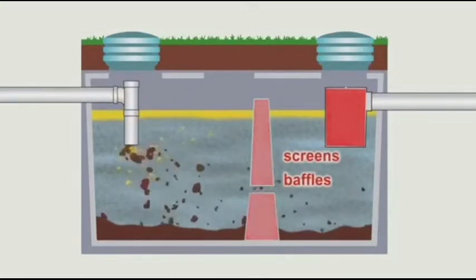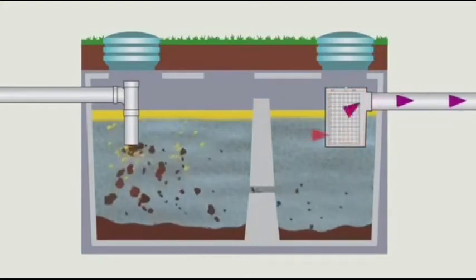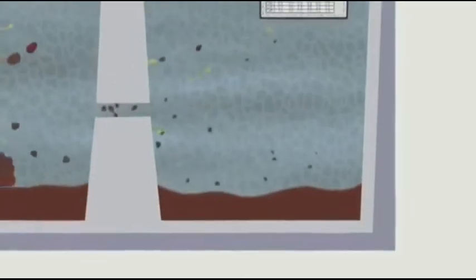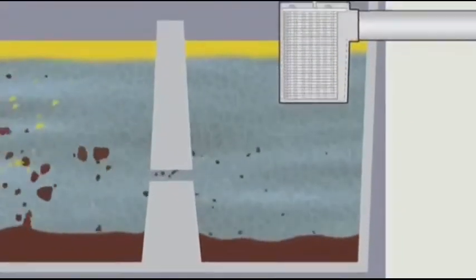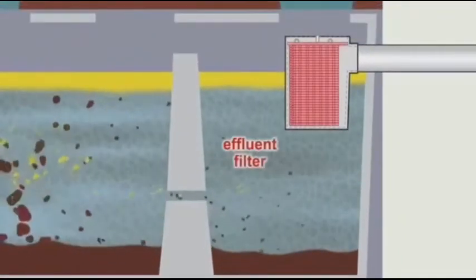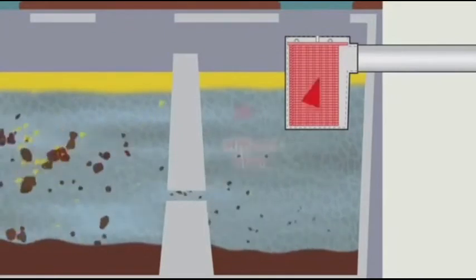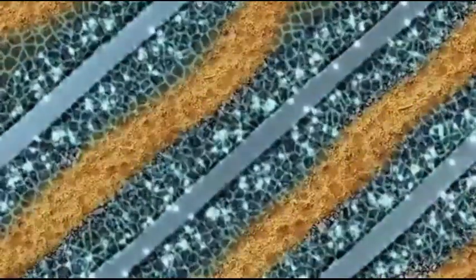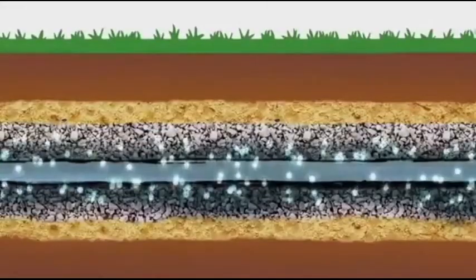How do the cluster septic systems work? The sewage flows to the septic tanks at each residence. Then the septic tanks retain scum and solid waste while they convey the liquid sewage to a treatment and dispersal system, and finally to a drain field for soil-based treatment.